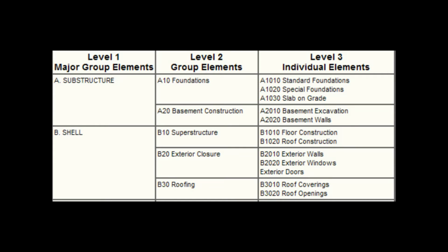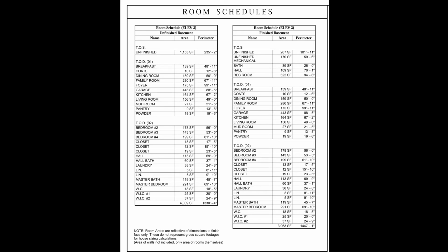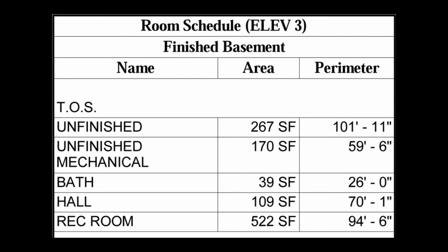As a result of all of this, you can schedule anything. Anyone in the construction industry is used to seeing door schedules and window schedules, but you can literally schedule anything. You can drill down and schedule the perimeter of a room so that you're getting the base trim, and obviously all the area components. So you can actually schedule all the pieces and parts and have sort of a parts kit with your project.